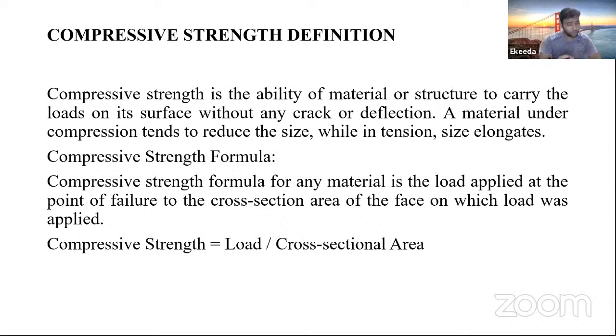Yes. Okay, that's why I had written the formula here: compressive strength is equal to load divided by the cross sectional area, and the cross sectional area will always remain 15 centimeter into 15 centimeter, because we always prepare the cube of 15 into 15 into 15.